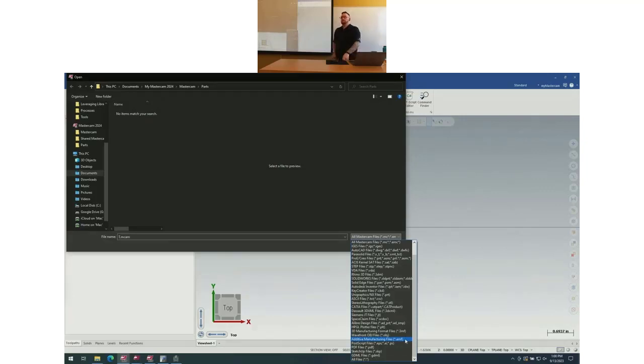Mastercam cannot convert a mesh into a solid. That is correct. We actually do offer a different product that does that. SpaceClaim ANSYS. You can do it in Verisurf. So there's a couple of ways to go about it if you do need to convert that into a solid for some reason. But a lot of times you could make an STL work for the application. If you're running into something specific, let us know.